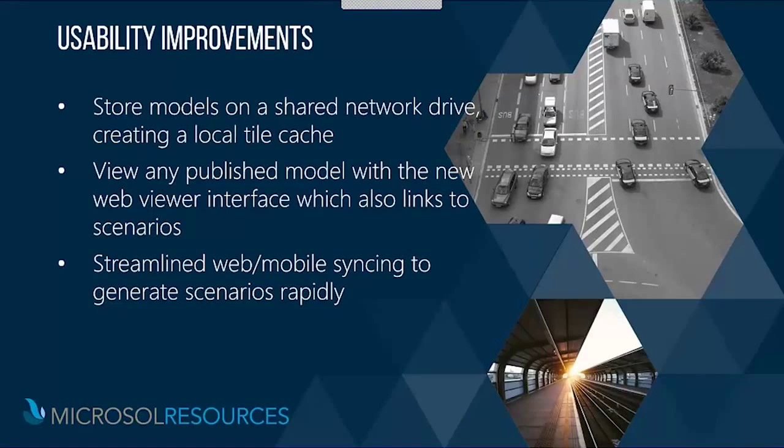Now, the reason being that most of the SQLite information that gets stored for that is there's a ton of files that get written constantly. Now, if that's stored on a network location, you can experience some degradation in performance. And if there are many people using InfraWorks models on a shared network, it could create latency issues, it could create bandwidth issues. Now, one of the newer features is the ability to create a local tile cache.